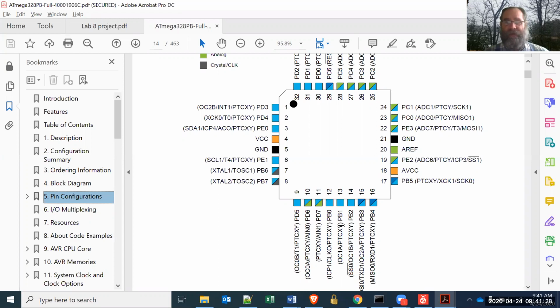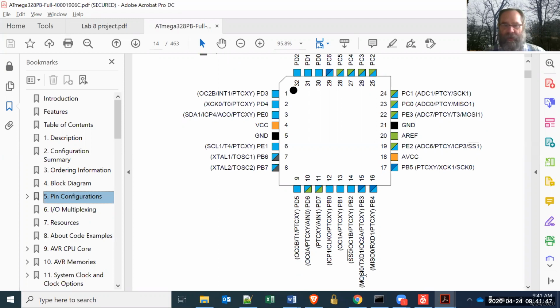Timer 1 is the only thing that can control port B1, which controls the green LED, and timer 2 on B3, OC2A, that controls the blue LED. So you have to use 3 different timers.